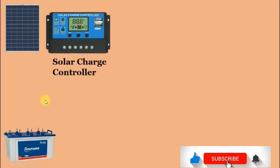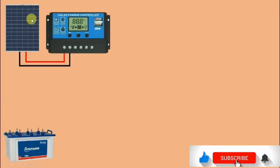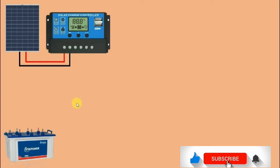One of the components is the charge controller. The charge controller is a device that is meant to regulate the amount of charge that's stored in the battery. The charge controller is connected to the solar panel, and reduces the amount of voltage that is passing through to the battery. Now the battery serves as an energy storage device for this voltage that comes from the panel, and then it is distributed to a load, say a DC bulb.